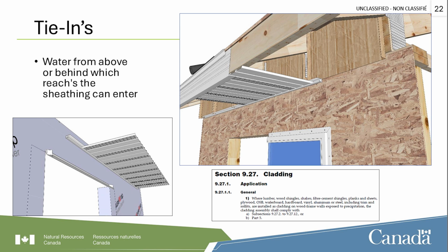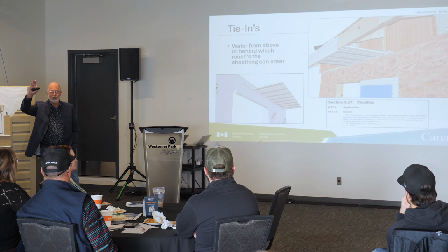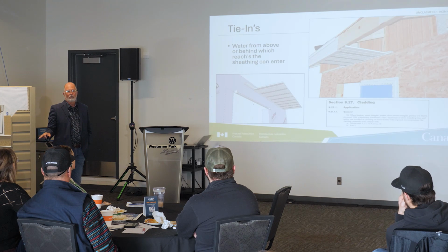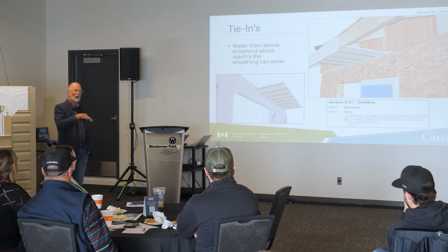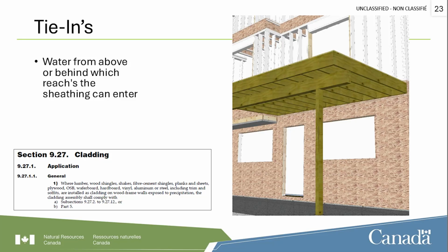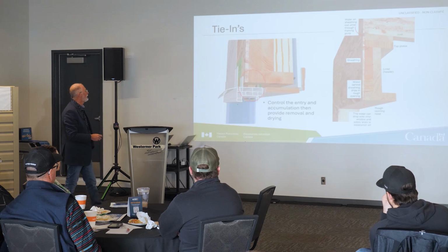into the basement. And the amount of times we found this lets water into the second or the main floor windows. The upper windows are protected, but it hits the joint in the sheathing, it comes in the main floor windows, and you're going, everybody's doing water tests on the window. Well, no, it's coming in from the soffits. And it's all the way down. So again, that sill protection protects you if the water gets in there. Same principle behind decks, right? If we don't have proper membranes at decks and the water gets behind, finds a joint in the sheathing, it's into the rough opening. So that's why sill protection and protection of that rough opening is so important.